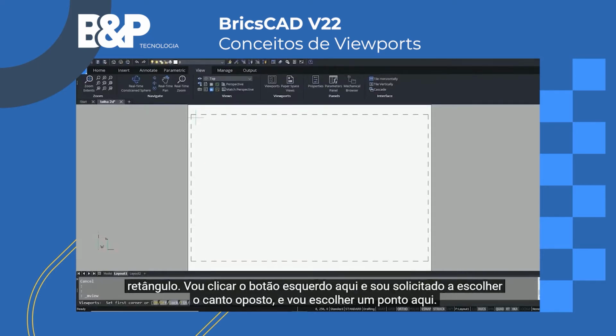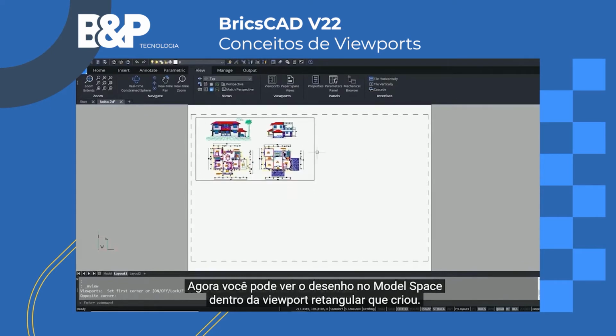I'm asked to select the first corner of this rectangle. I'll left click here. Now I'm asked to select the opposite corner. I'll pick a point over here. Now you can see the drawing in the model space within the rectangular viewport you have created.